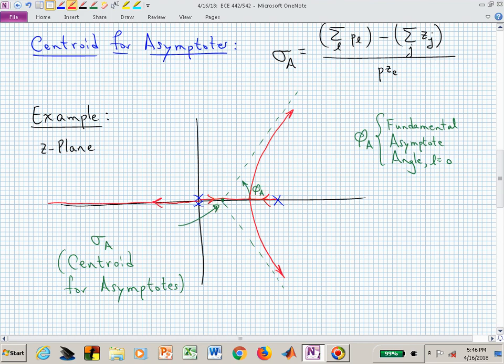But if I said, give me the rough sketch of the root locus, you could pretty quickly find the centroid and those asymptote angles, sketch those, and now that gives you guidelines with which to sketch the 2 branches that you know are departing or breaking away from the real line between the origin and that rightmost pole.